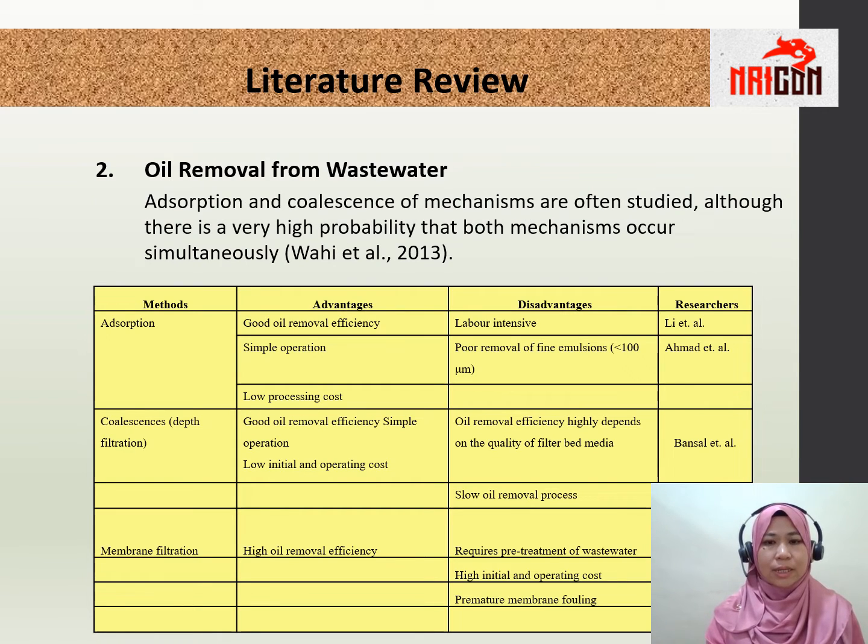Okay, according to Wahi et al. 2013, adsorption and coalescence mechanisms are often studied, although there is a very high probability that both mechanisms occur simultaneously. The advantages and disadvantages of adsorption are shown in the table. The advantages of the adsorption process are good oil removal efficiency, simple operation, and low processing cost. The disadvantages of the adsorption process are that it is labor intensive and has poor removal of fine emulsion less than 100 micrometer, according to Lee et al. and Ahmad et al. respectively.